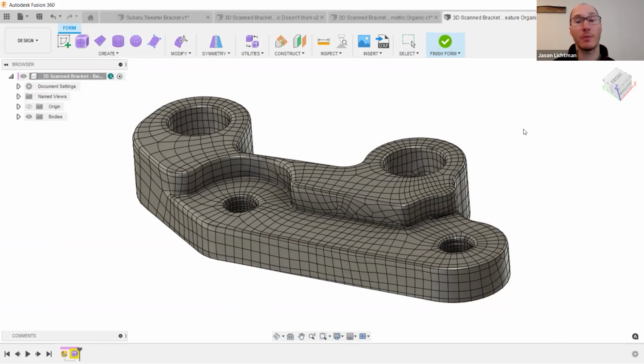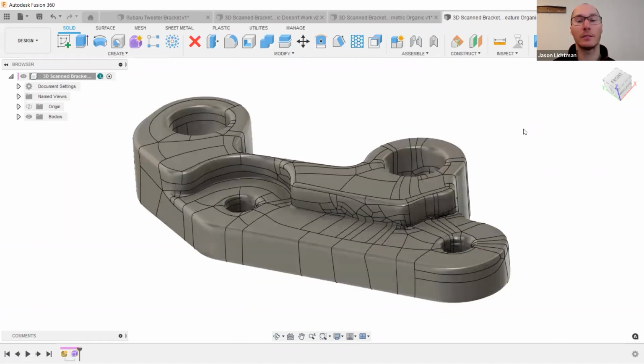And if I fix my problem, I'm now going to get a solid body with as few faces as possible. So you're not going to get the exact number of faces as you saw on the form. You're going to get fewer, which is a good thing. Most importantly, though, at this point, I have a solid body. So again, I could use this for a variety of different purposes. But again, to compare and contrast between the parametric and the base feature, the parametric option is, of course, parametric.